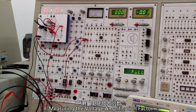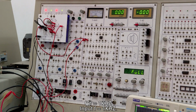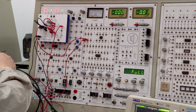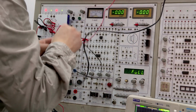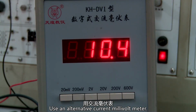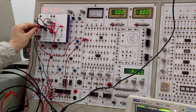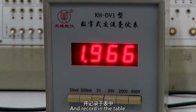Measuring the voltage amplification factor. 1. Turn on the signal generator. Input a 1 kHz sine wave signal with an amplitude of 20 mV. The output end is open-circuited. Use an alternating current millivoltmeter to measure the size of Ui and Uo respectively, and record in the table.